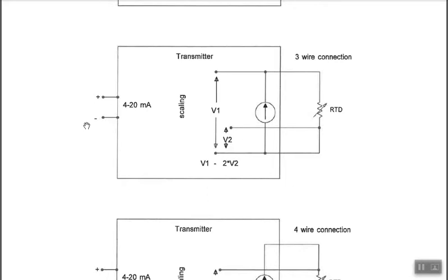Now we're going to talk about the 2, 3, 4-wire output side of the transmitter, and you can see why the fundamentals are important to nail down, because you've got 2, 3, or 4-wire connection options on the input of the transmitter with the RTD type input, and now we've got 2, 3, 4-wire connections on the output side of the transmitter.